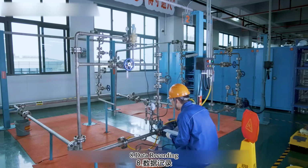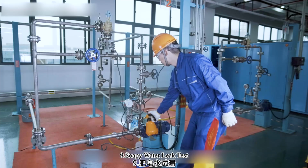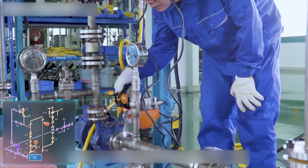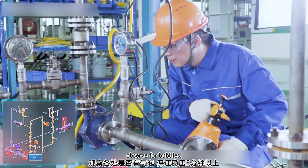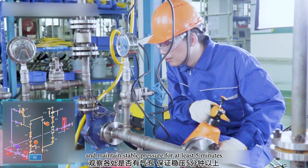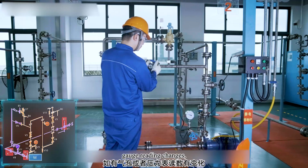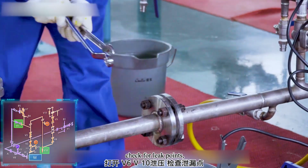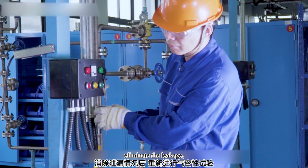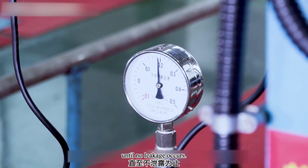Eighth, data recording. Record the pressure gauge reading every 2 minutes. Ninth, soapy water leak test. Spray soapy water on positions A, B1, and B2. Observe for bubbles, and maintain stable pressure for at least 5 minutes. If bubbles appear or the pressure gauge reading changes, open V6 and V10 for pressure relief. Check for leak points. Eliminate the leakage, and repeat the air tightness test until no leakage occurs.